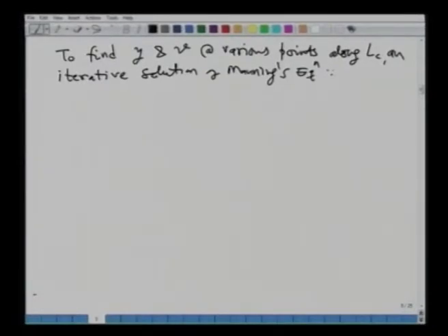Well, what is the Manning's equation? You know that Q is equal to 1.49. We will do this for the FPS system, which can be easily extended to the SI system. R to the 2/3 S to the half, where S is S0, and this is my equation number 5.6.12.